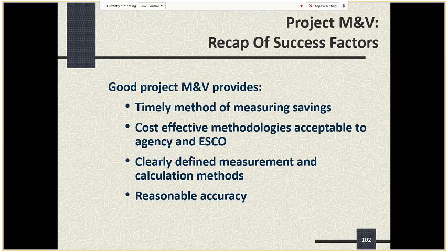So converting over to a two-way valve allowed us to convert to a variable pumping schematic for those energy savings opportunity. Yep. And then on top of that, it was pneumatic actuation for a large percentage of the valves. And so we went with full electrical or electronic actuation and full DDC on the fan systems.